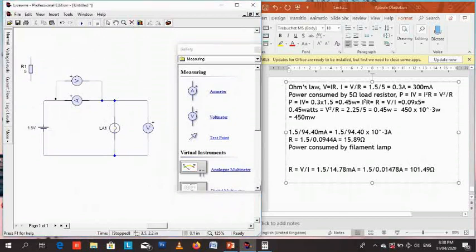Now, if I measure the voltage across the ammeter, it's 9.94 microvolts. That is so small. It's infinitesimal. That should not be enough to account for the great drop from 1.5 to 1.36. Ideally, the voltage across the lamp should be 1.5 volts, but for some reason the voltage dropped. I'm trying to see if you can measure across the cable. It says 0 volts, but according to LiveWire, the voltage dropped to 1.36 volts between here and here.